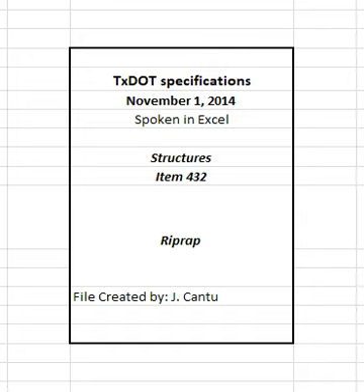2.2 Pneumatically placed concrete riprap. Use Class 1I concrete that meets Item 431, pneumatically placed concrete, unless otherwise shown on the plans. 2.3 Stone riprap. Use durable natural stone with a bulk specific gravity of at least 2.50 as determined by TxDOT 403A unless otherwise shown on the plans.